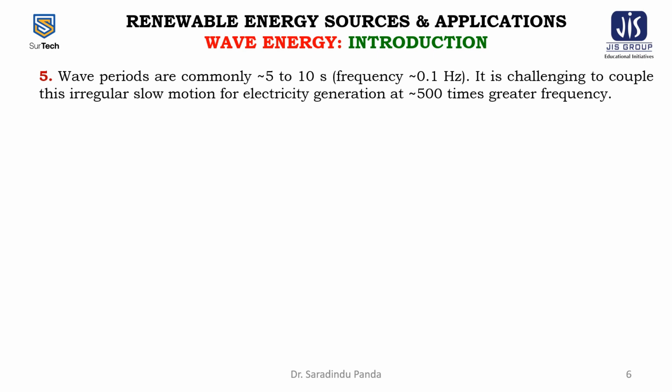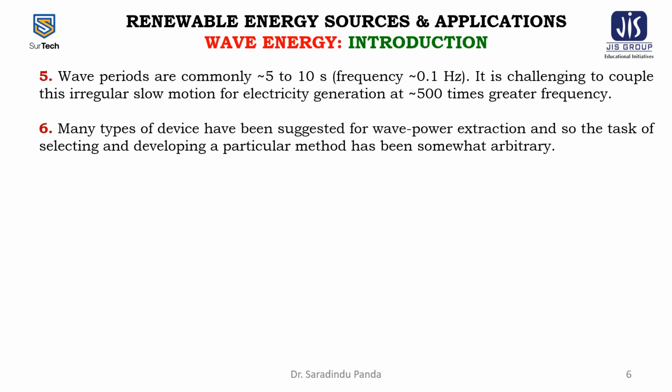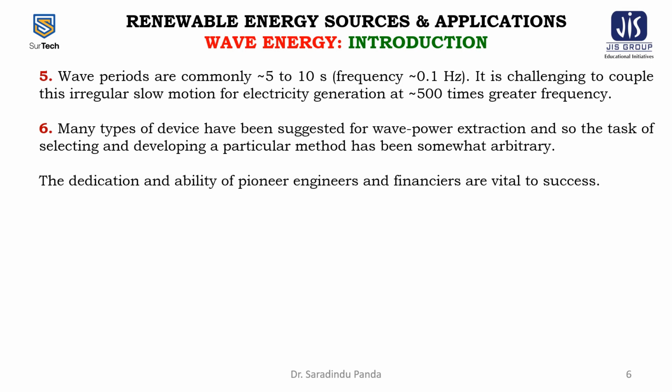5. The wave periods are commonly 5 to 10 seconds. It is challenging to couple this irregular slow motion for electricity generation at 500 times greater frequency. 6. Many types of devices have been suggested for wave power extraction, and so the task of selecting and developing a particular method has been somewhat arbitrary. The dedication and ability of the pioneer engineers and the financiers are vital to success.